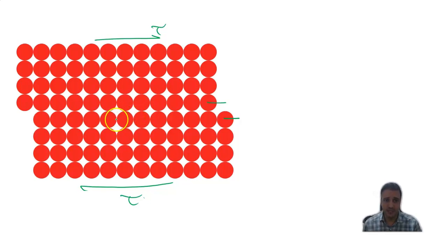And this breakage of the atomic bonds needs a lot of work and a lot of energy. But in practice, the amount of work and energy that we need for plastic deformation is much lower than the theoretical value that we calculate for breakage of these atomic bonds. So there should be another phenomenon that facilitates this plastic deformation and the slip of the crystallographic planes.